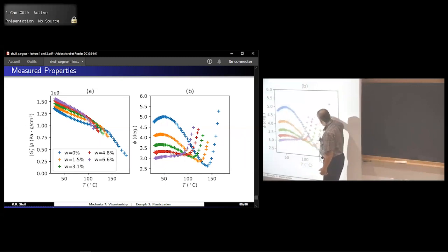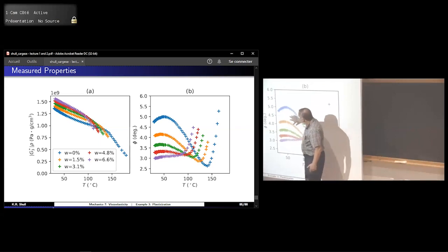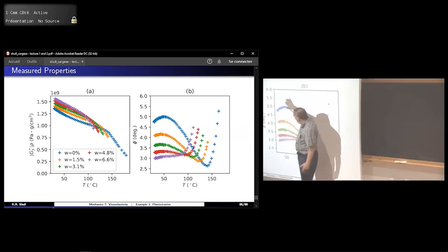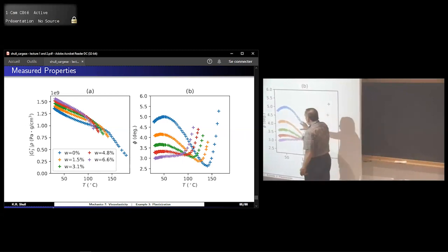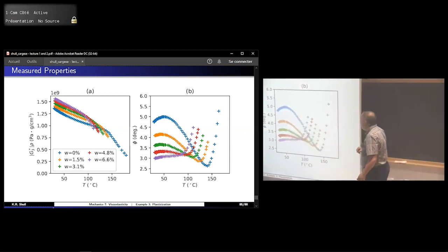So this is the signature of the glass transition. It should be around 150 degrees for polycarbonate. And as we add more plasticizer, we're driving it down this way. And there's this fairly large sub-Tg relaxation peak here, which is presumably relevant for mechanical properties and toughness of something like polycarbonate. So it's very easy to see this in these high-frequency measurements. So that was the only point there.